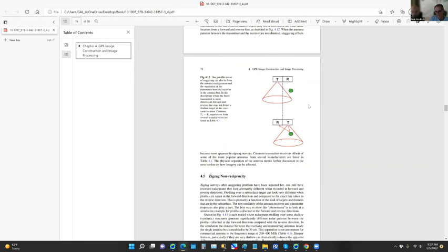Some people would say that by going in two different directions, or zigzag, you record all the different features in the ground, even though they're not identical line to line. Some people prefer to go back to the beginning of the line and collect data so that they all have the same characteristics. You can sometimes see what looks like an artificial staggering in the data, even though the positions are slightly changed, because you've done a zigzag survey.